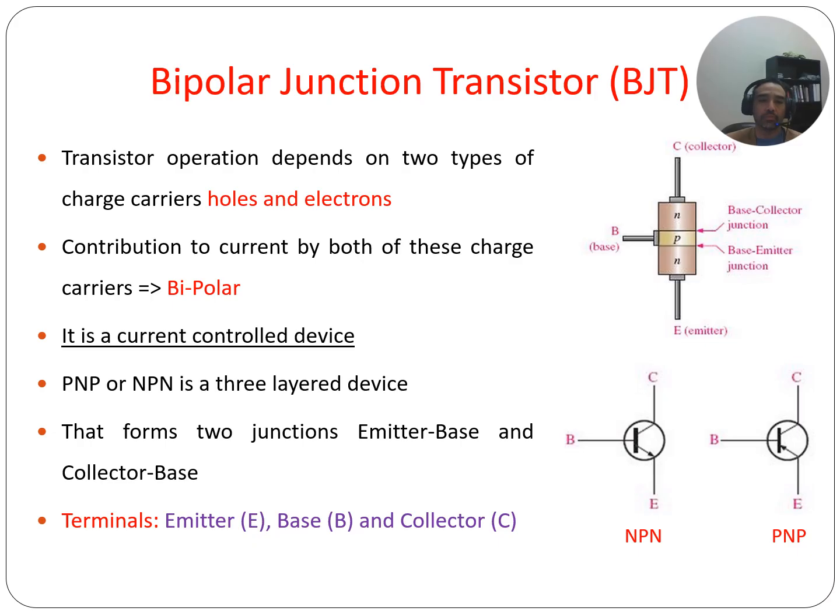So in a transistor, you have both electrons and holes, and that helps move electrical current, right? So you say, how does a hole help move electrical current? Well, you can't move an electron into a space that's already occupied. So by having holes, you create an opportunity for something to move. And so we call these bipolar transistors because they use both types of charge carriers.